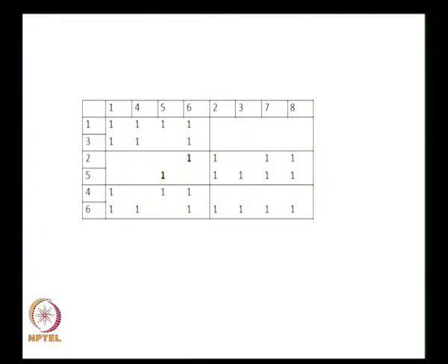So, when we do this, we could have a solution that has machines 4 and 6 going into the remainder cell with 2 intercell moves. The final solution will be 1 4 5 6 come here, 2 3 part families are intact, but we realize that 4 and 6 go into the remainder cell with 2 intercell moves, when the remainder cell has a capacity of 2. Let us just check that.